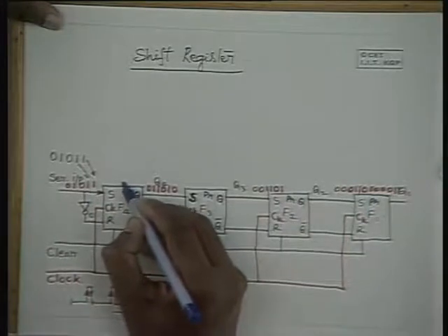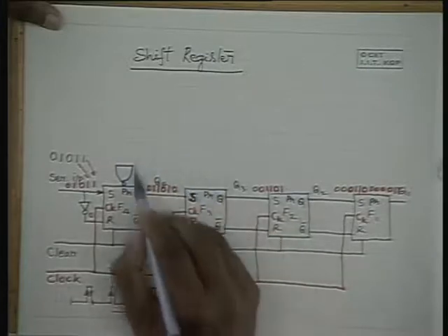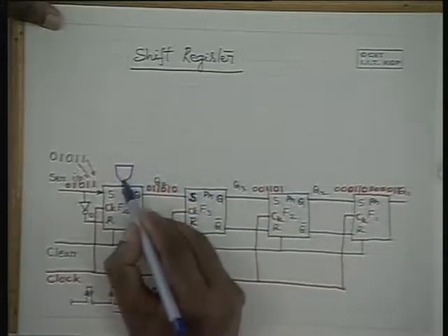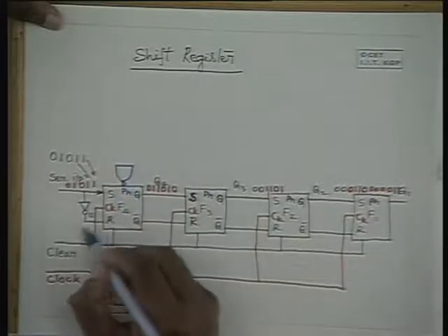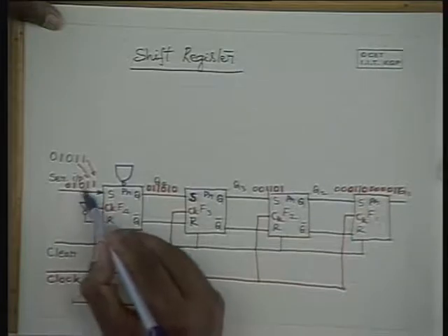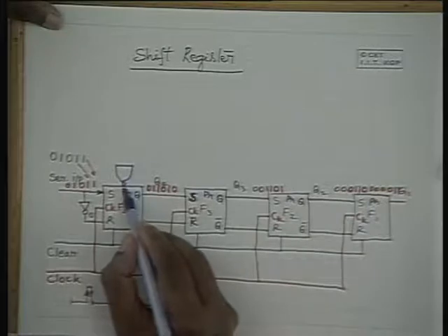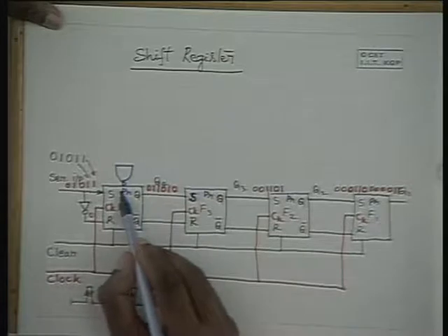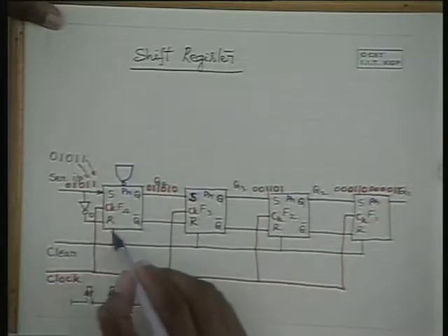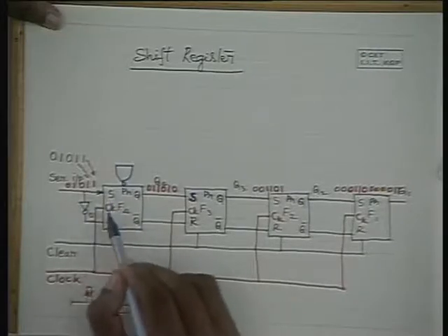Now in some shift registers, it can be sensitive to the low level here. The moment a low input appears here, irrespective of the inputs and irrespective of the clock pulses, the moment the preset is a 0, output will be 1 for the flip-flop. That means the preset input and the clear inputs, as I mentioned earlier, override the SR inputs.